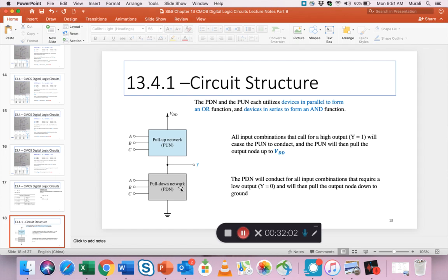Generally, so far we have seen maybe 1 or 2 transistors, right? NMOS at the bottom, and that's the pull-down combination. And PMOS on the top, that's the pull-up combination. You can have 1, 2, 3, 10, however many on the top, but you must have an equal number on the bottom. That's the way they work in the CMOS world, right?